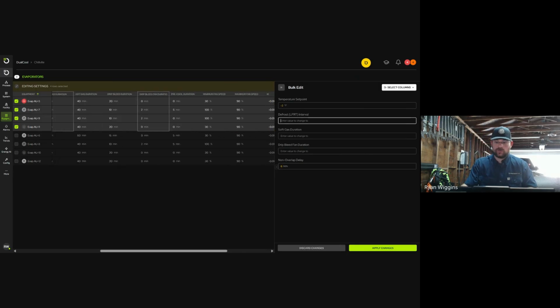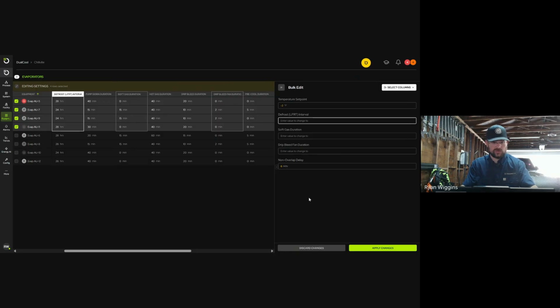From here, I'm going to change that setting. We're going to go back to the liquid feed runtime. We're going to change it to, we'll say 15 minutes. Oh, sorry, 24 hours. And I don't know if you guys noticed, when I changed the settings for the liquid feed runtime to 24 hours, there's only 2 yellow boxes here. That is because for evaporator 7 and 9, that setting was already set to 24 hours. So it's only going to highlight boxes where the value has changed.